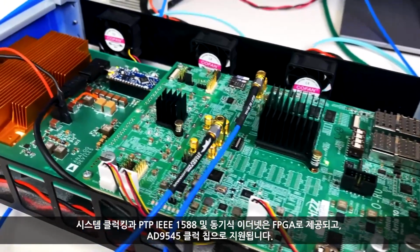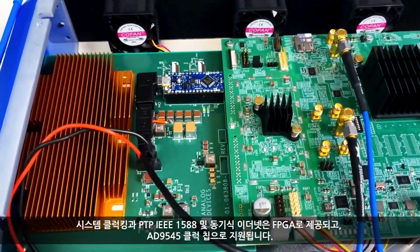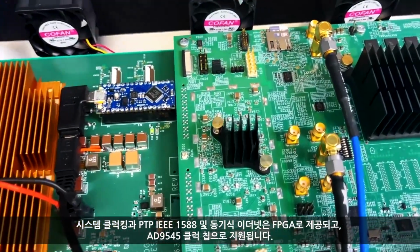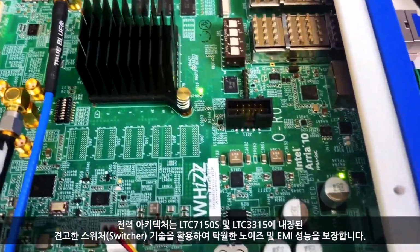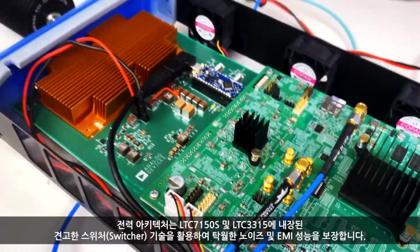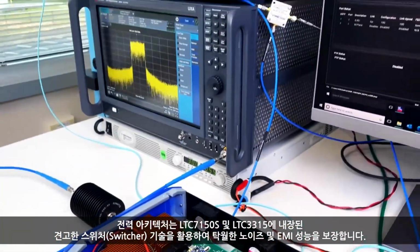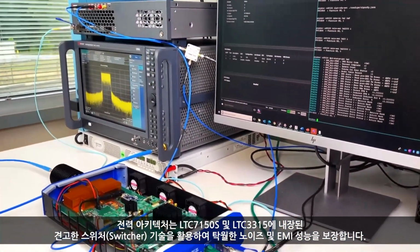System clocking, PTP, IEEE 1588, and synchronous Ethernet are provided by the FPGA and supported by the AD9545 clock chip. The power architecture takes advantage of the silent switcher technology included in the LTC7150S and the LTC3315 to ensure excellent noise and EMI performance.